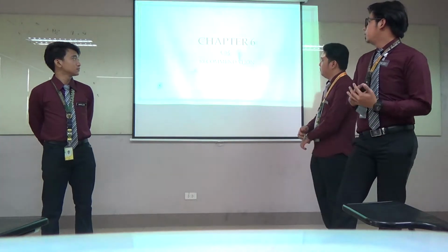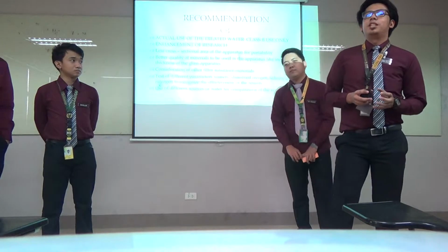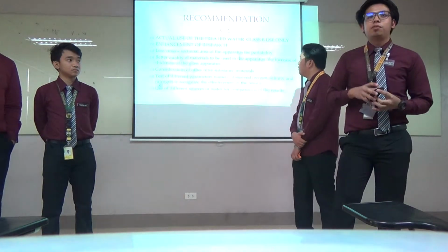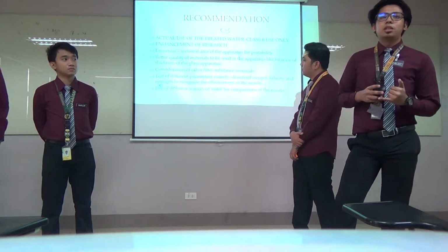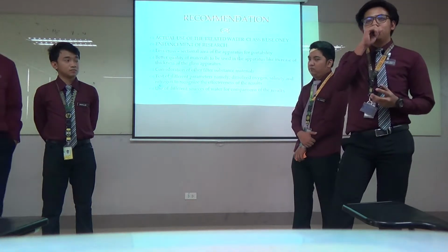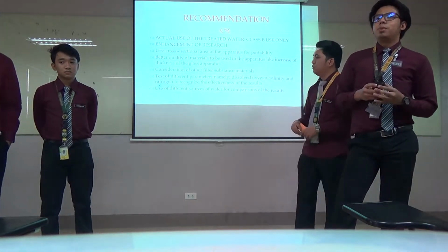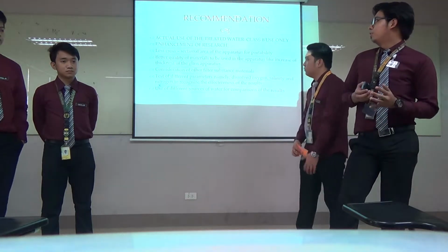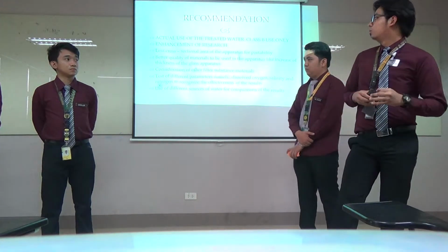So for the recommendation, even though the water can be classified up to class A, the researcher recommends it only for class B use, or only for household uses and not for drinking purposes. The reason is that to be considered potable water, it needs to meet the national standard for drinking water of the Philippines. So it needs further treatment like sedimentation, disinfection, and more.